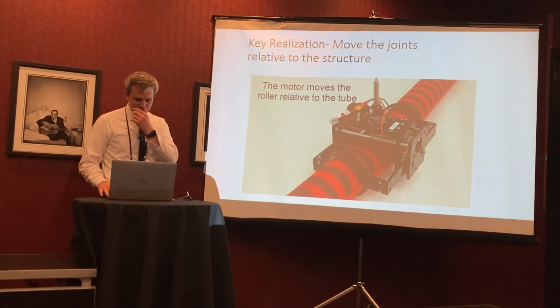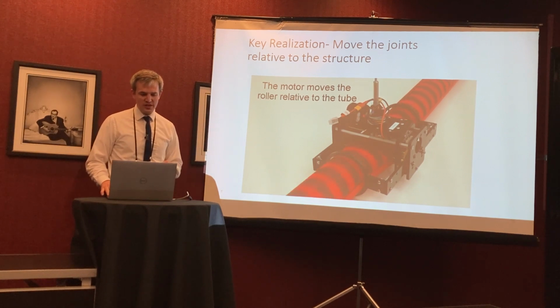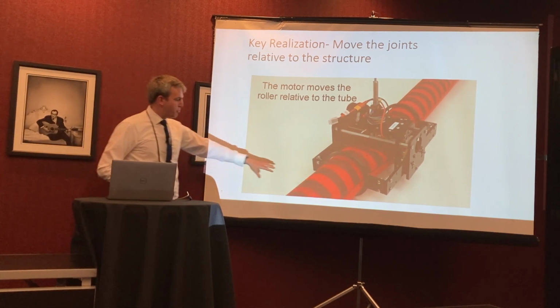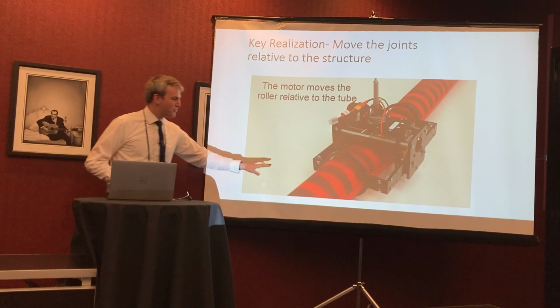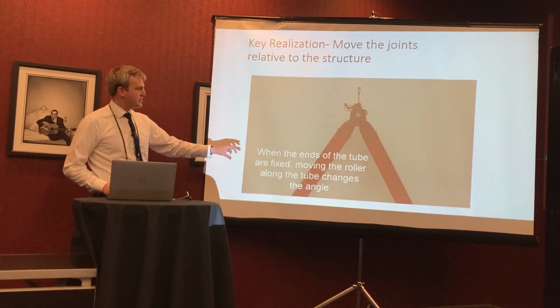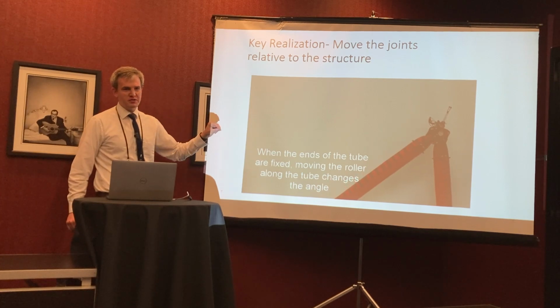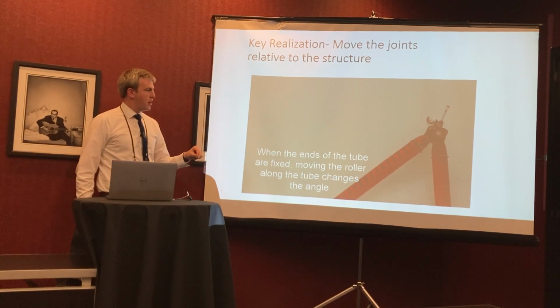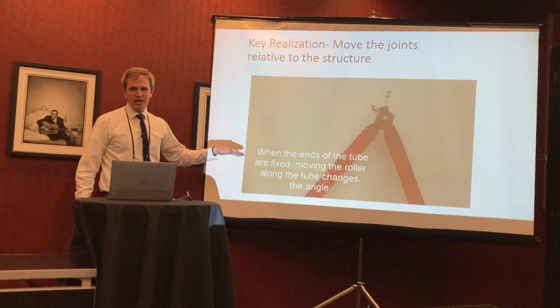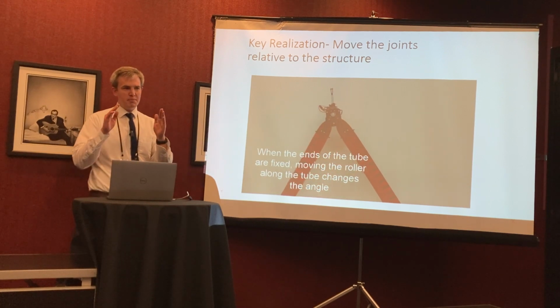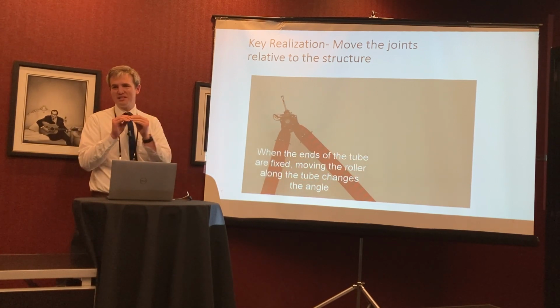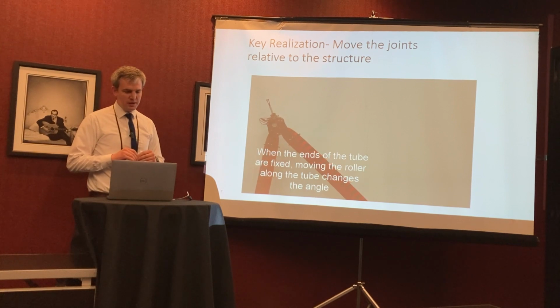Physically, we're able to realize this system as something that looks like this. This red portion here with the tiger stripes is an inflated fabric tube. And this is a little cart robot that essentially pinches that tube and drives back and forth along the tube. It allows air to flow from side to side, but what this basically does is it creates a point of low bending stiffness that acts as an effective joint in this continuous beam.